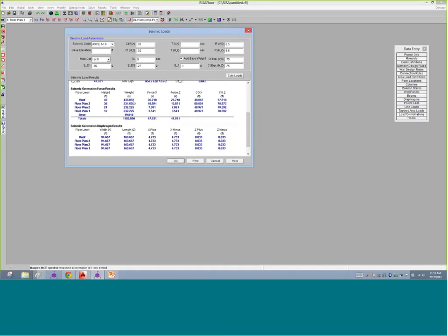But what I always also like to do is a back of the envelope check on myself, on my hand calcs: does that weight of that structure jive with what I think it should be? If it does not, then all of these calculations to follow are not going to be right. So I might want to go back to RISAFloor and make sure I modeled that properly and put the superimposed dead load, or what we call that dyne load, properly. Otherwise, I might not get the right forces in the X and the Z direction. So this is why I like to use this weight column as a sanity check of, yep, that looks about what I would expect that floor weight to be, and then we go from there.